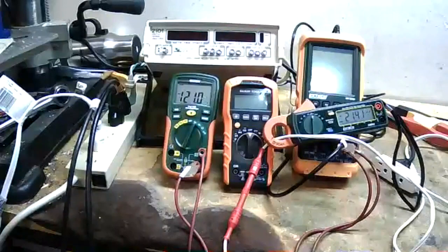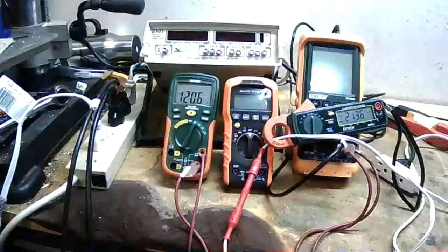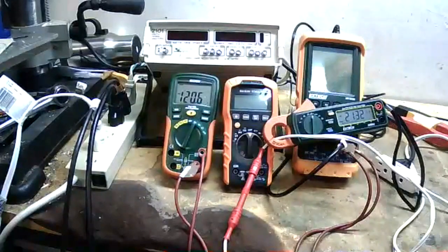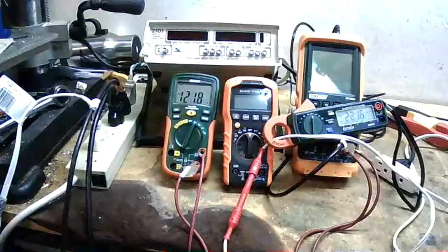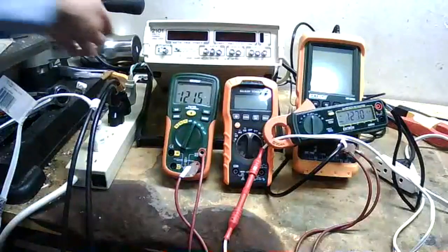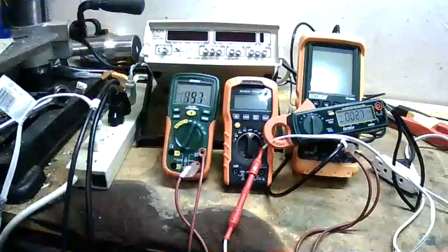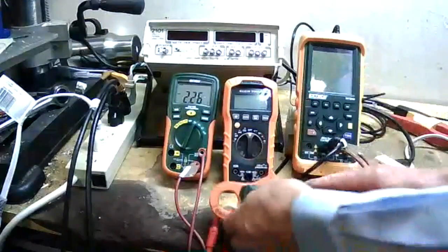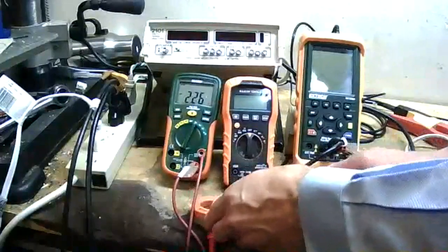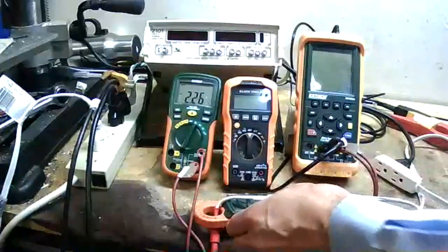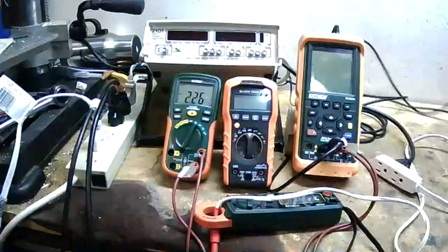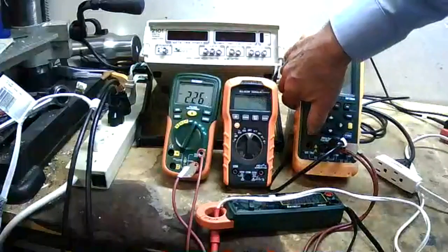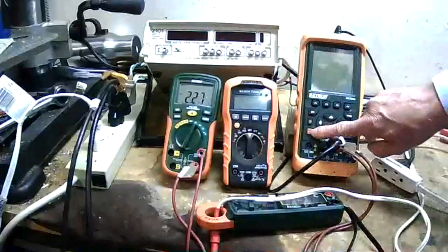That's how we can measure the current in the circuit without actually breaking the circuit, which in power and energy applications is often very important. We still need to measure the phase angle so that we can calculate the real power. One way to do that is using an oscilloscope. And I have a very nice handheld oscilloscope here.